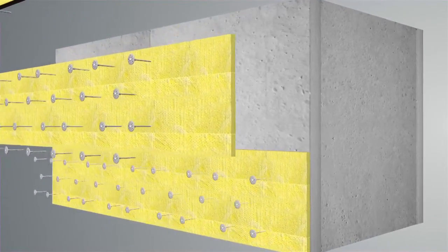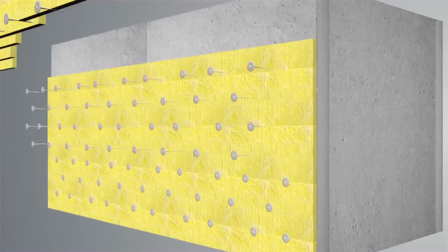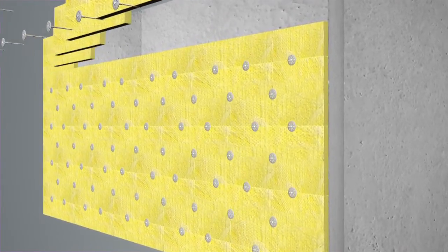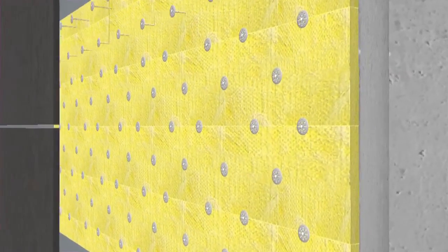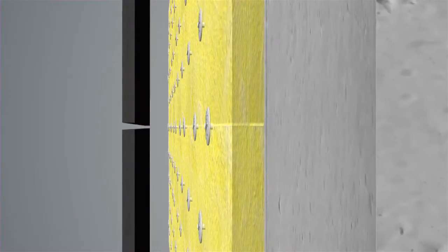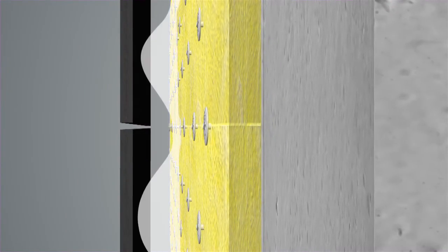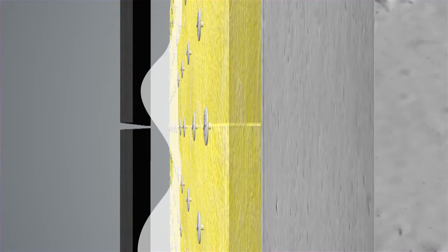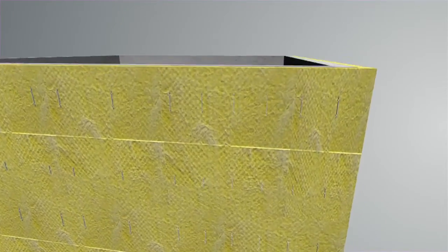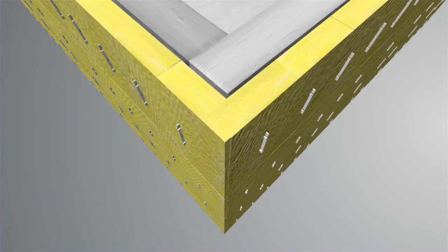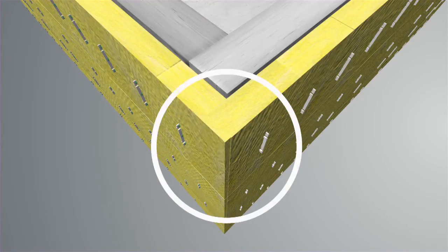Whichever insulation board is chosen, they must all be securely fixed to the structure, which is normally with special fastenings. Over time, the insulation must not sag or bulge out to block the air cavity. It is important that the insulation has no gaps at its joints and fits tightly around the subconstruction to reduce heat loss and the effect of cold bridging.